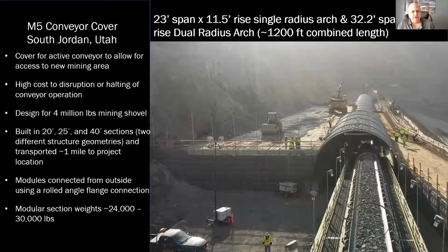The larger structure was pre-assembled in 20 and 25-foot long sections, and the smaller arch was pre-assembled in 40-foot sections up in a laydown area, and then transported about a mile to where the project site was. And then from there, set on the footing and then connected to each other as they go. And all of the work on site around the conveyor is done from the outside of the structure. Individual weights of the modules, in this case, range between about 24,000 and 30,000 pounds.